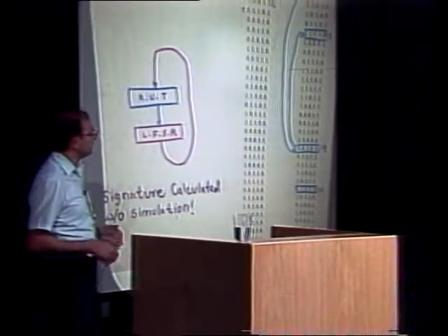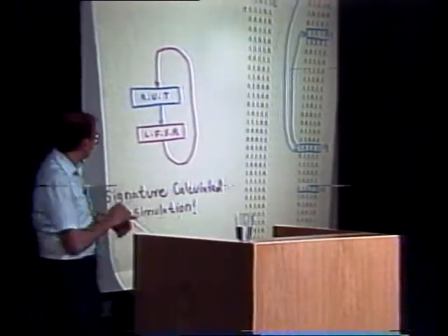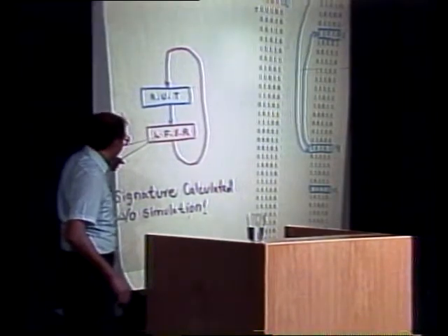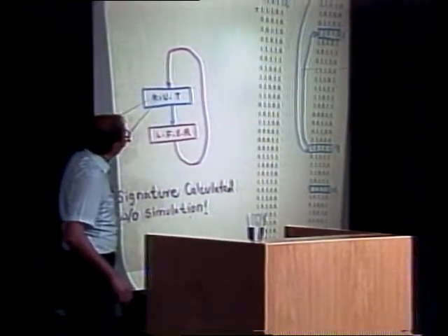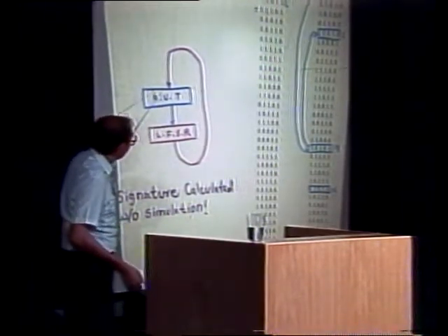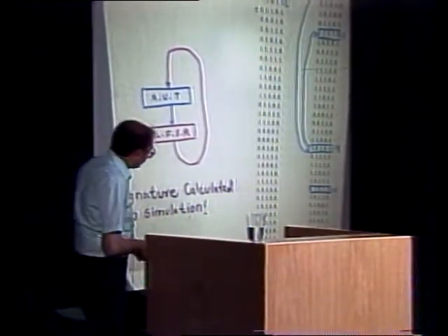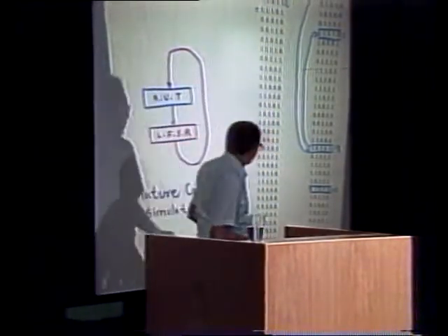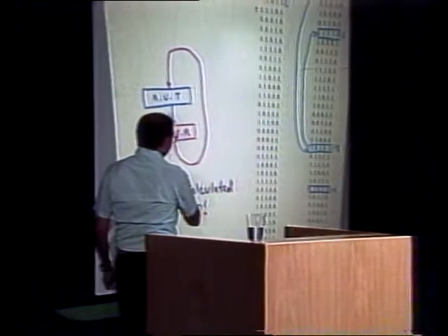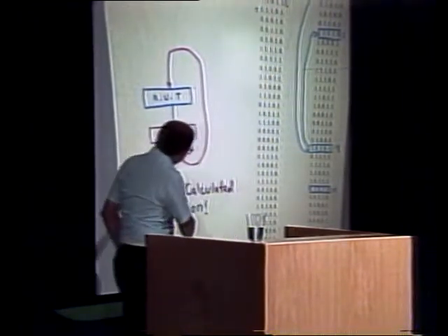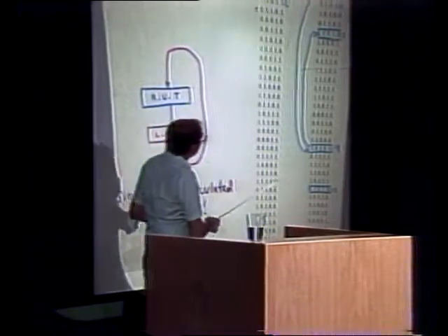let it go to the signature. Then whatever is the state of this signature register or LFSR, put it back into the register, read it back, generate the next state, and put it back. If you do it like this, this is what happens. If this was the original test sequence with the linear feedback shift register run in autonomous mode, when we run it in this mode, this is what happens.